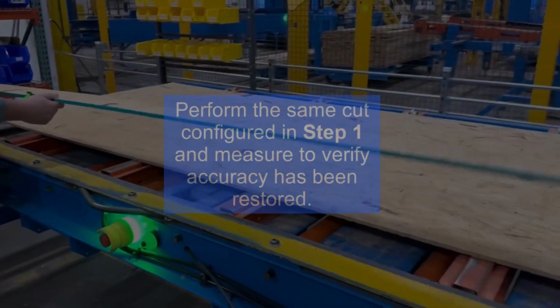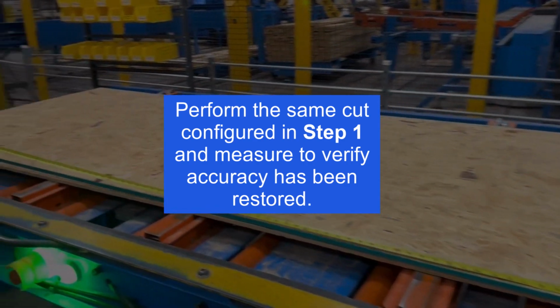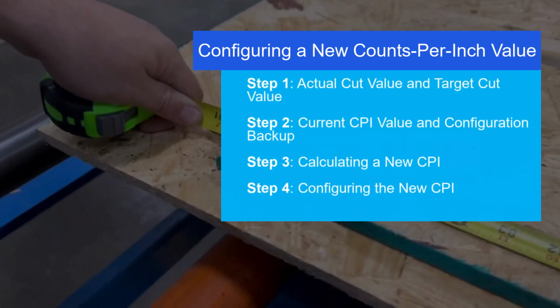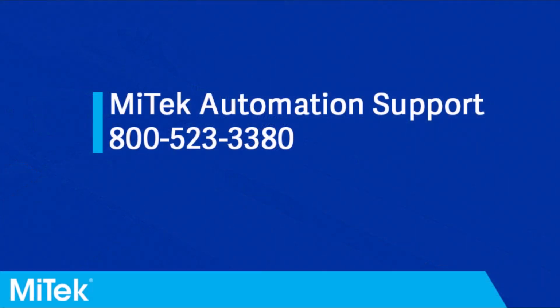Perform an identical cut on the same material as used in Step 1. As before, measure the crosscut for accuracy. If the cut is still not accurate, follow Steps 1 to 4 to configure a new counts per inch value again, or contact automation support. If you have any questions or need further assistance, please contact automation support.